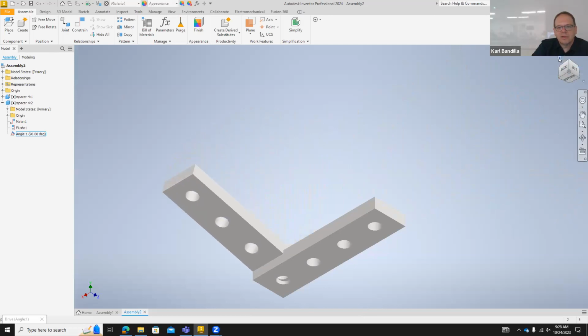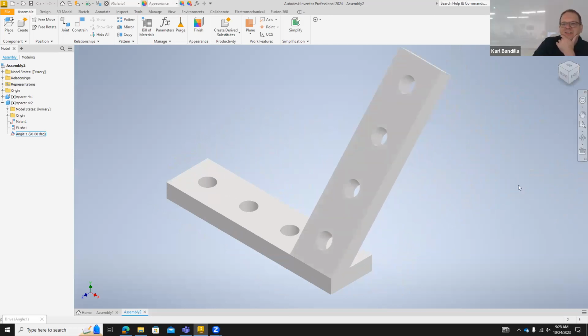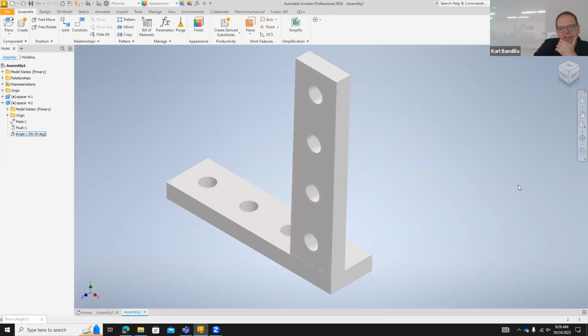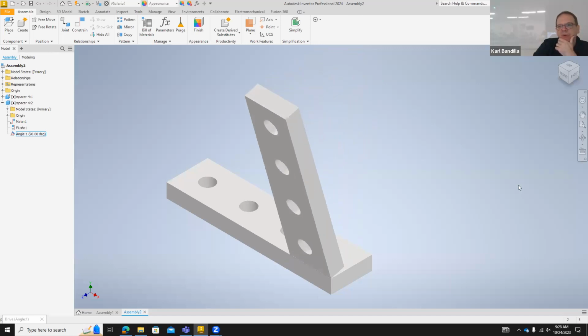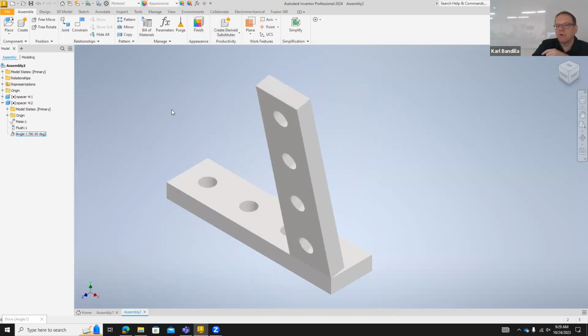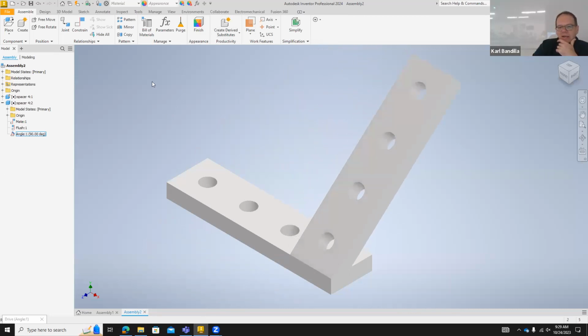Back to the original view. I should have reduced the amount of movements, but we'll just wait for it to finish. Now, when you're doing this, especially with the AVI file, it is important that you close the little window that pops up at the end. If you don't close the drive window, then it will not release that file. It will hold on to that file, you won't be able to find it anywhere. So you have to hit the OK or the cancel button.